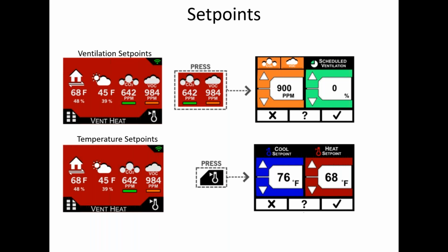And then you're also going to be setting the heating and cooling set points. This will dictate those heating and cooling modes of operation that the system can do as well. So the recirculation heating, recirculation cooling, as well as the free heating and free cooling modes of operation.